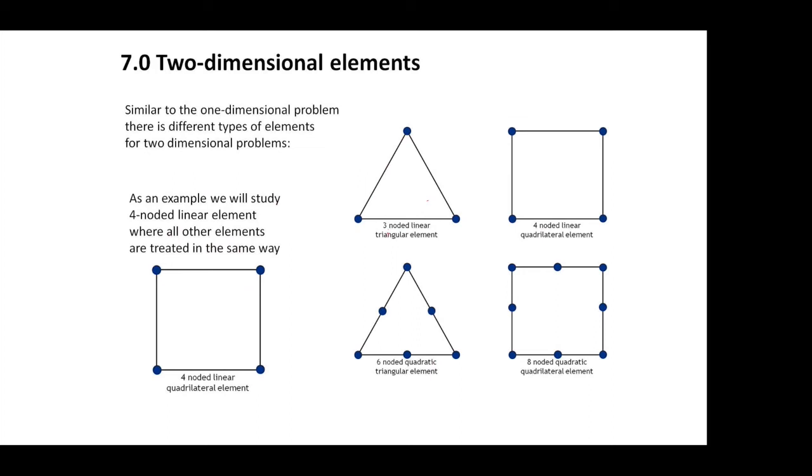So we have discussed the 3-noded element. This is linear element, and we discussed four-noded elements. We call it linear, but it is a bilinear element because if you look into the shape functions, they are multiplications of two coordinates. So it is not an equation for a plane. A truly linear element is this three-noded element because the shape function is really a plane.